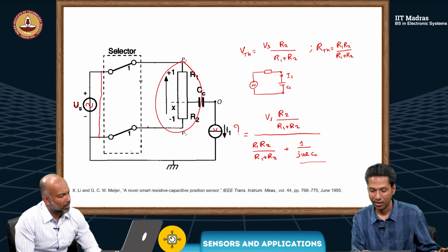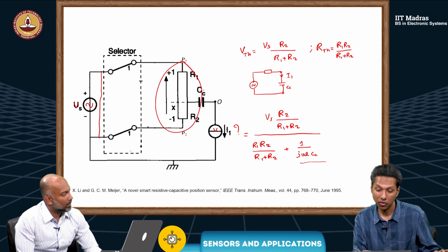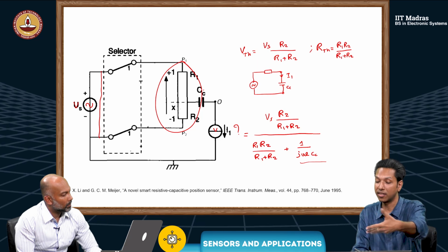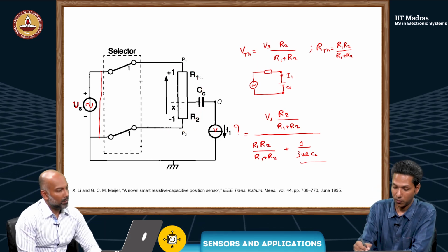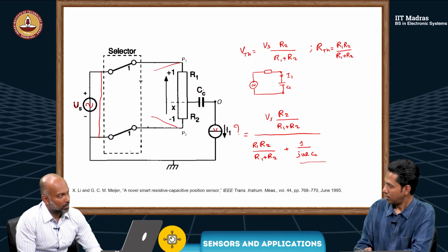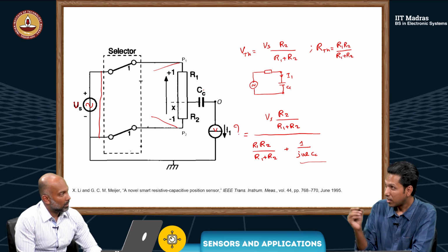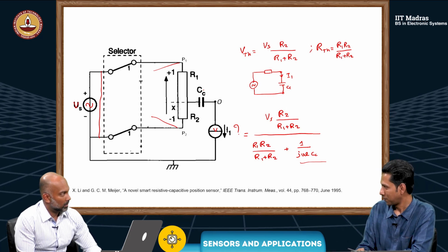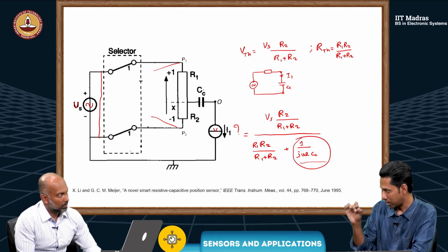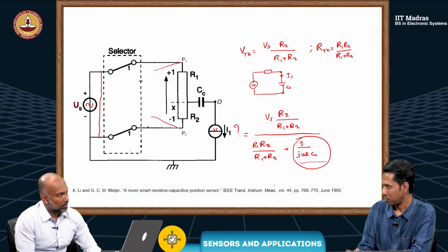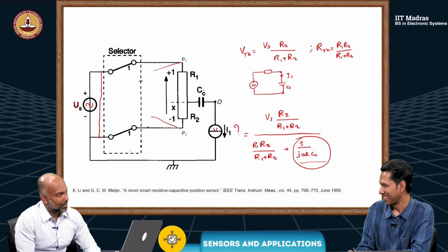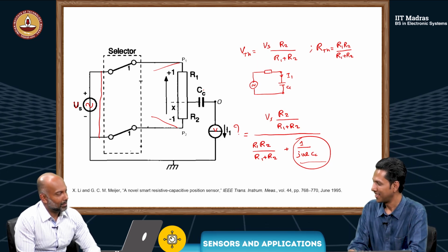When I say flip, I'm going to flip the excitation to P1 and P2, so I'll interchange these two excitations. Which means the Thevenin equivalent resistance will remain the same, and if I measure the current there, the denominator will be the same. So it will cancel. There is a possibility. The numerator will be different. We'll try that.